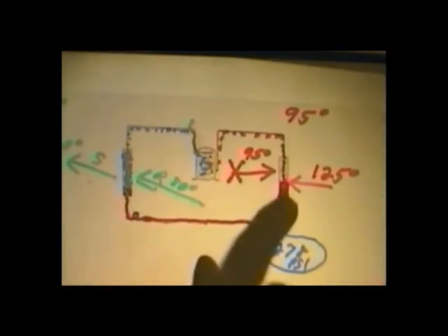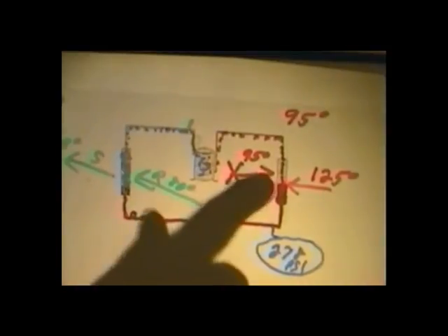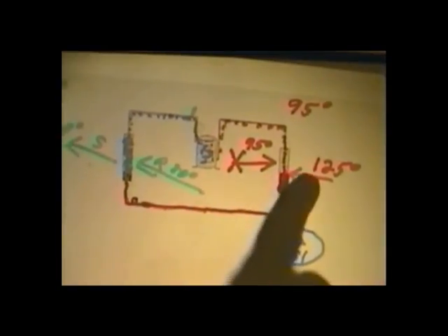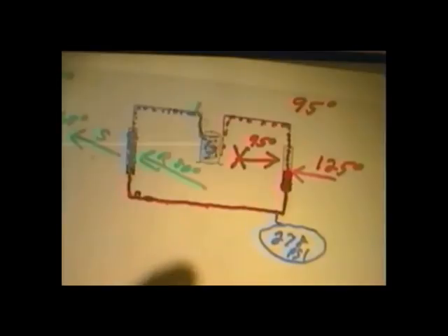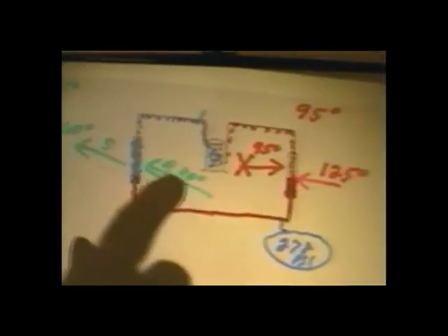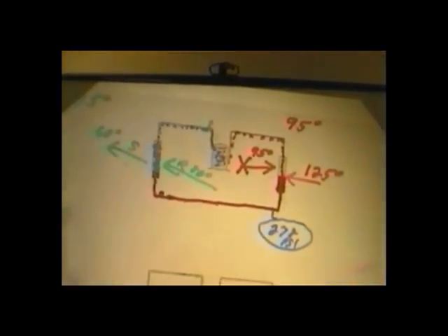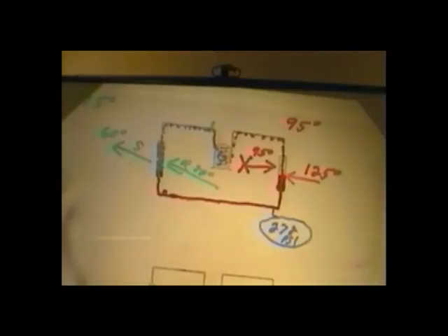It all means the same thing. That's the saturated line. It's condensing. Okay? So we know that that's 125 degrees. Now, let's go over to the low side. We said that we had an 80 degree return and a 60 degree supply, and it's working terrific. That's about a 20 degree difference.